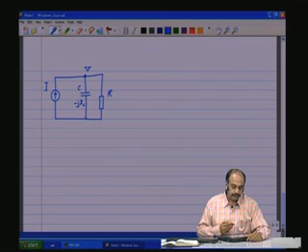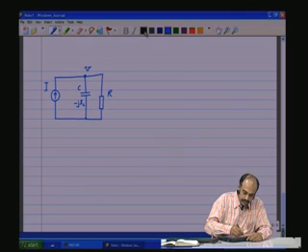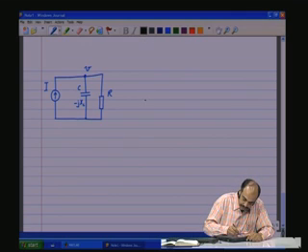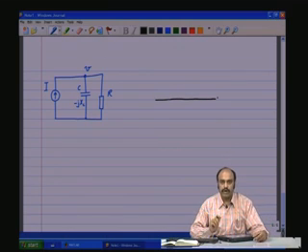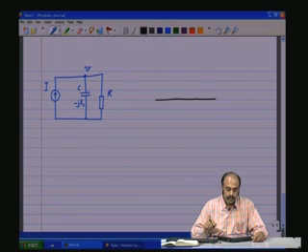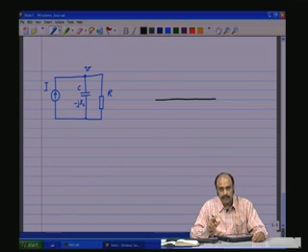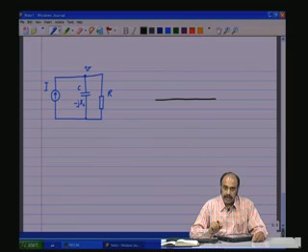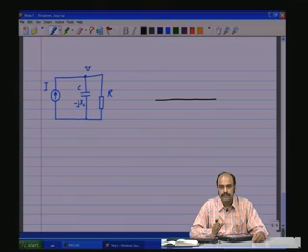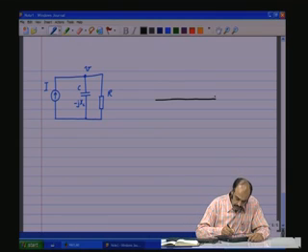Now, let us draw the phasor diagram for this. Let us first have an axis. So, all our phasor diagrams are in the spatial coordinates, and note that the phasor diagrams in the spatial coordinates can be mapped onto the temporal coordinates, which will result in the actual wave shapes, and the phasor diagrams will give you a picture at an instant of various wave shapes relative to one another taken with respect to some reference. So, let us have a reference.